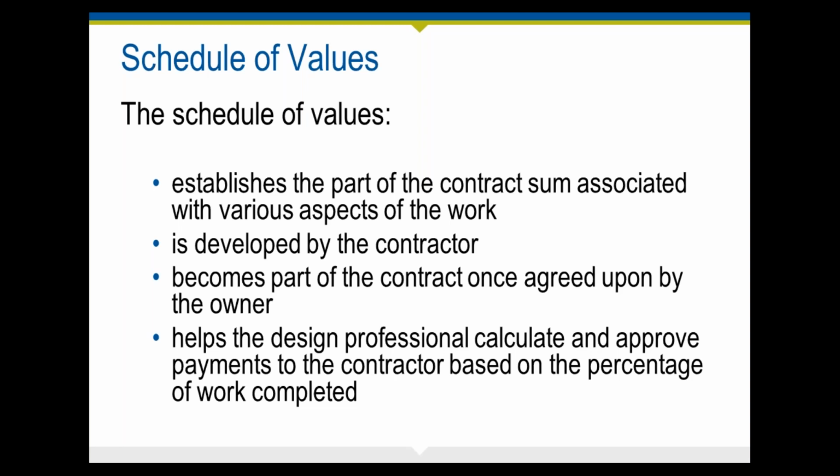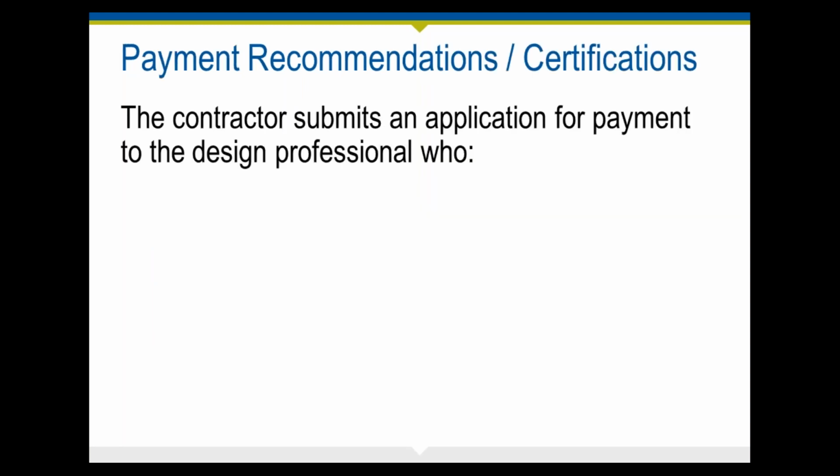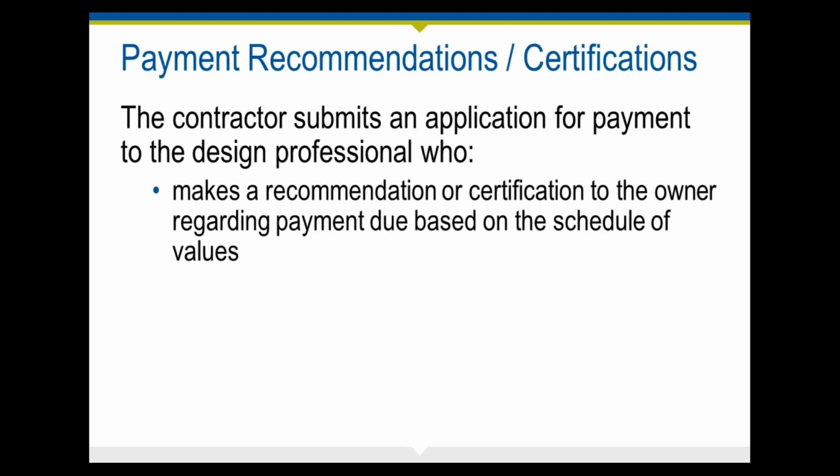So if you have that, it's developed by the contractor, the owner accepts it, it helps you calculate and approve payments to the contractor based on the percentage of work that has been completed. So always use that whenever you're being asked to do recommendations or certifications for payment. So how that works is they submit a pay app, and you make a recommendation or certification to the owner based on the schedule of values.